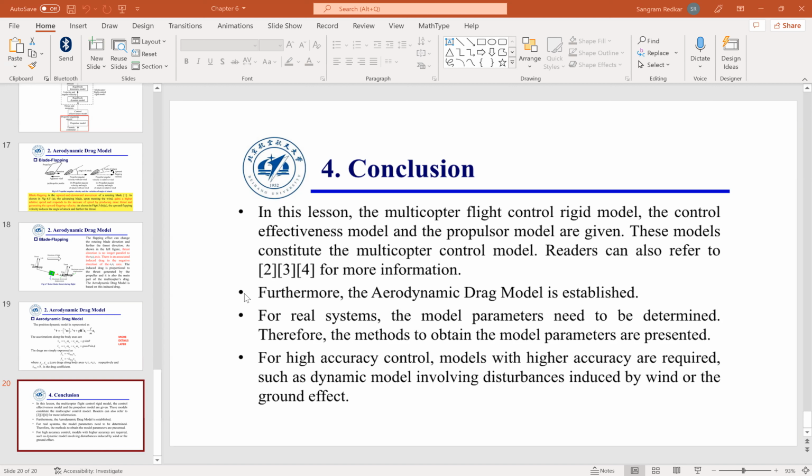Now you may say, oh wow, what happened now? So now you have this transformation matrix. Remember, there were three angles. There was an initial rotation about yaw, then rotation about pitch, and then rotation about roll. Can you see that all those, 0R1, 1R2, 2R3, got combined and you got this big rotation transformation? Everyone understood this? A minute to think. It's the same transformation that I derived in the last class. Remember MATLAB? Euler angles. Everyone clear about this equation?